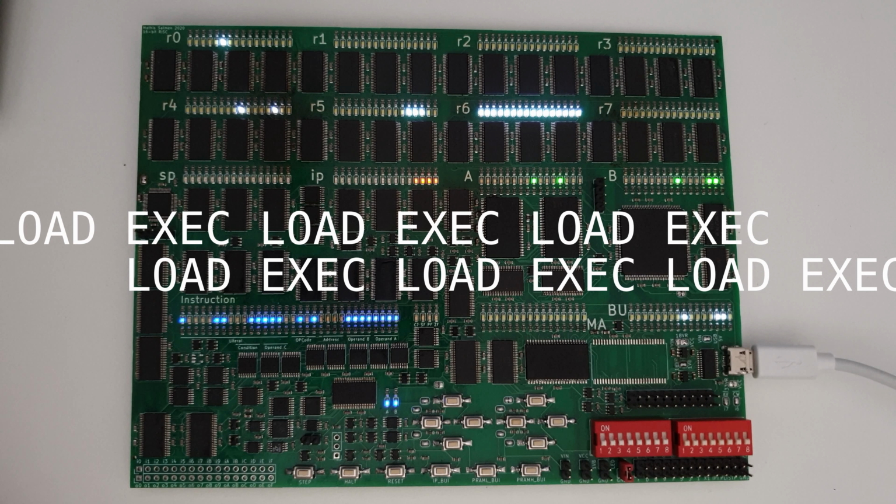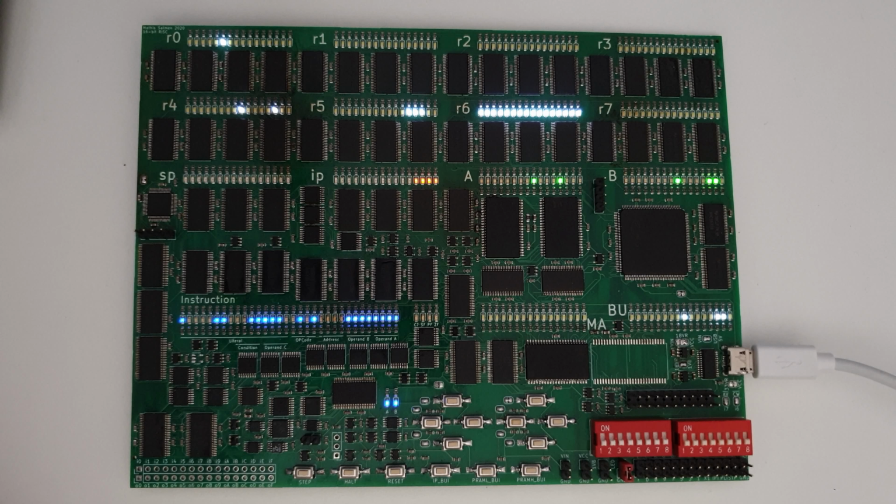To do this, I needed to adjust the hardware to make loading and executing work in parallel and in just one clock cycle. This added complexity is where most of the extra chips on our new design come from. For example, RAM for data and code is now split, such that we can load the next instruction from code RAM while also using data RAM to execute the current instruction. I made changes like this across the board to make every instruction run in one cycle, which really speeds up the design a lot, even when you run it at the same clock speed as the last one, and as you might have expected, the new design can also go a lot higher.